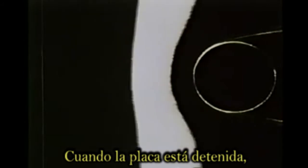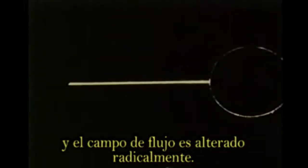When the plate is attached, a positive pressure gradient is imposed along the plate in the flow direction. This unfavorable pressure gradient causes boundary layer separation, and the flow field is radically altered.